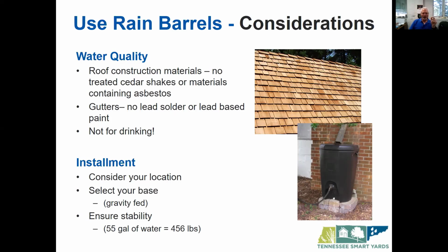We also want to be conscious of the overflow from the barrel when it fills with water. If the barrel is right beside the house foundation, the overflow from the barrel may go down toward the footer and could affect the foundation of the home. So our overflow needs to be carried away from the foundation.